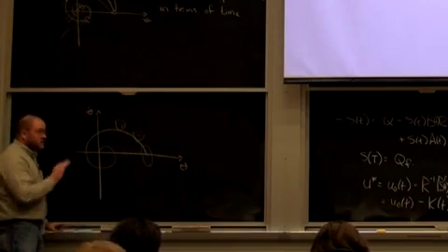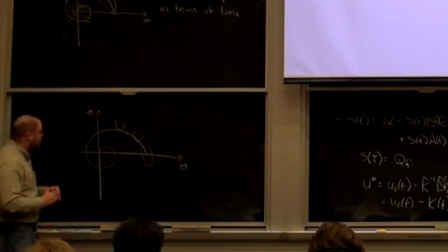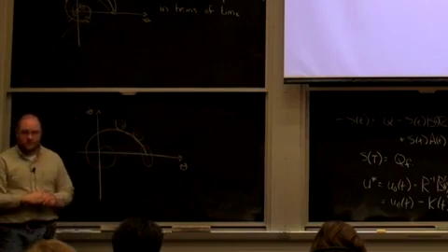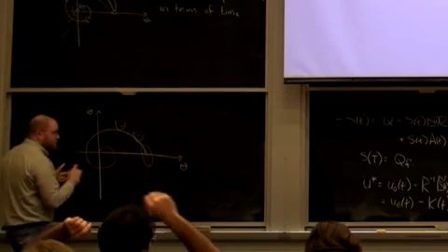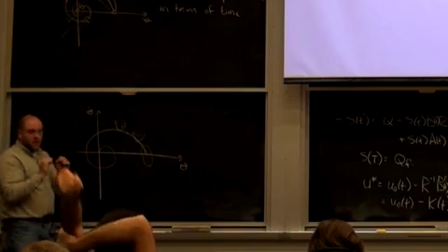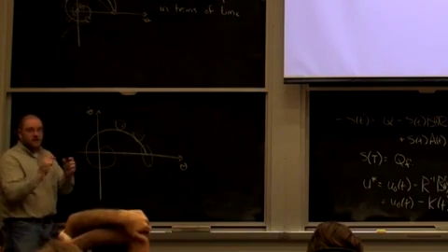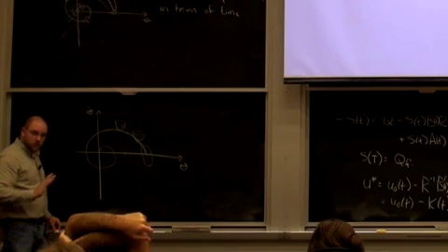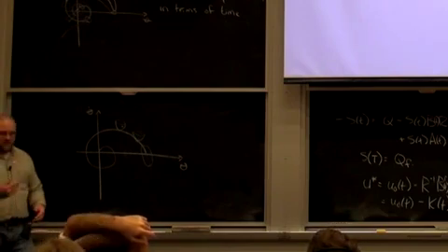And the key point is because I've reparameterized my equations in terms of x bar, this quadratic bowl always lives on that trajectory. Okay? My cost function was x bar transpose Q x bar. The best thing to do is to drive x bar to 0, which means to drive my system back to the trajectory. People okay with that imagery? It doesn't look like they are. Everybody is okay.